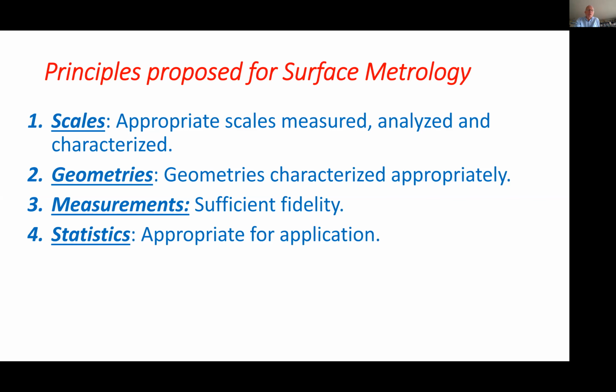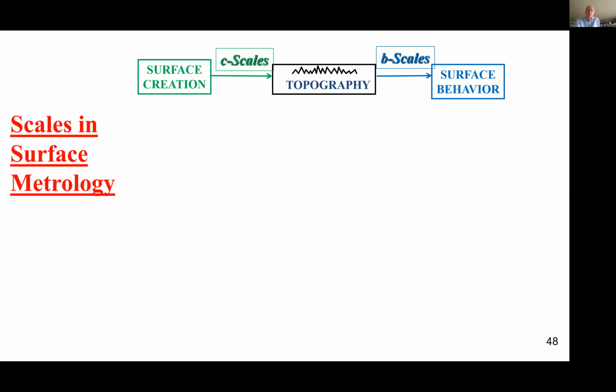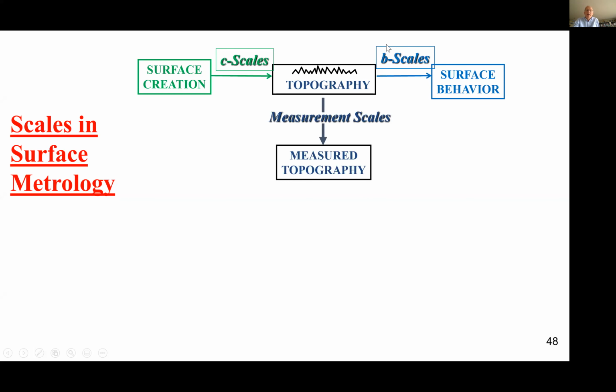So fatigue certainly is extreme values, but if I was to look at something else like adhesion, the mean might be important. So to sum this up, surfaces are created with certain mechanisms that impart certain scales on the topography. The topography interacts with the environment for its behavior, and that interaction is at some other scales. When we measure, there's measurement scales.